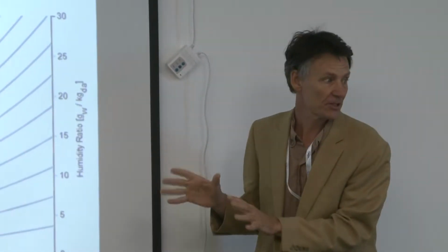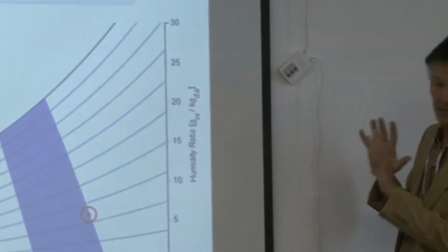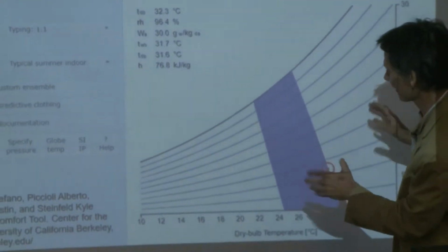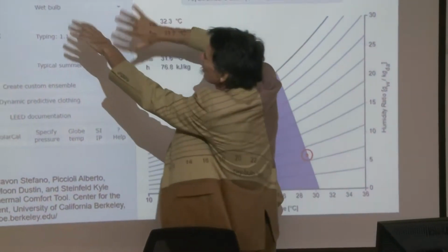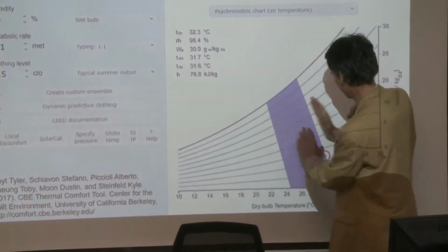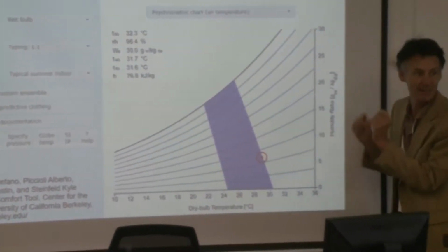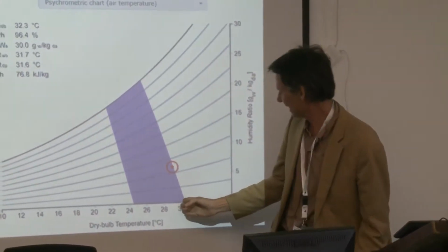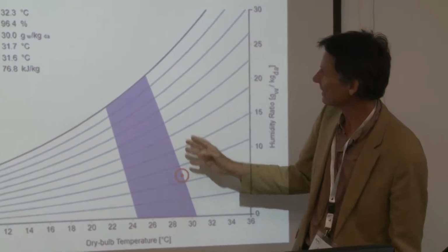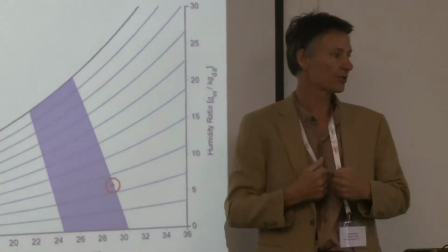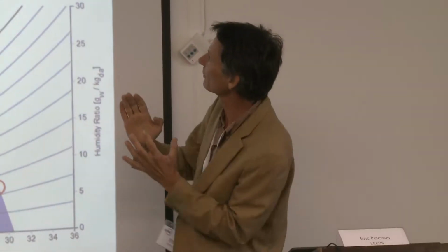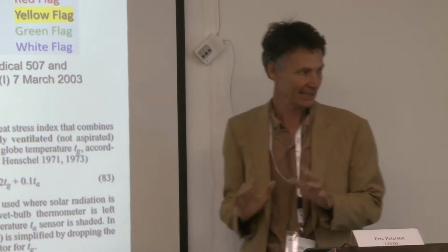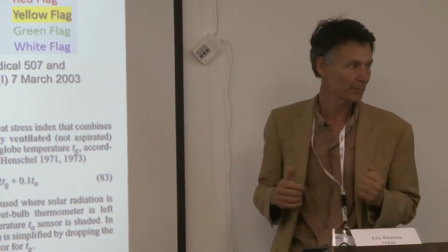So another University of California tool that's really useful is the Berkeley tool, which is the ASHRAE 55 adaptive thermal comfort tool. You can fiddle around with all this stuff with mean radiant temperatures, and you can find out whether you can just borderline make some set of conditions pass or not. The point is, though, that as you're getting towards 30 degrees C, you're going to have to increase airflow, reduce stress, all sorts of things to be able to tweak it. But when you're getting up over 27, it's tricky, touch and go. You've got to let people adapt.